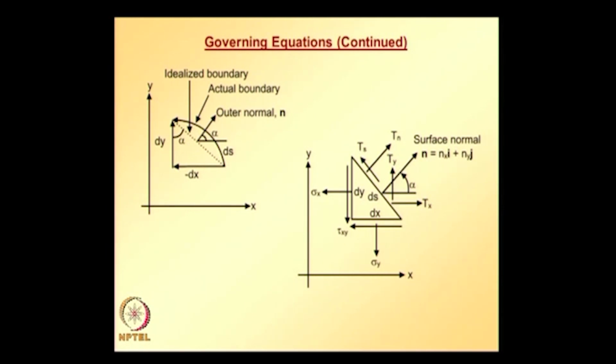So, looking at these two figures, we can easily write the relationship between T x, T y and T n, T s, and also the relation between the traction in the x direction, the traction in the y direction, and the stress components sigma x, sigma y, tau x y.